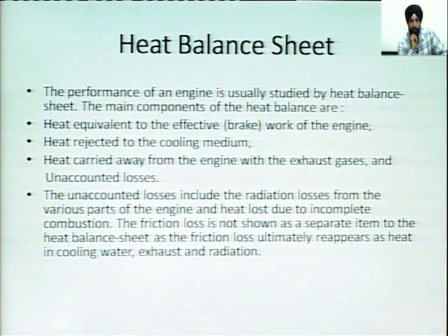The main components of the heat balance sheet are: the very first, heat equivalent to effective work of the engine or brake work of the engine. Second, heat rejected to the cooling medium or cooling water or coolant as the case may be. Third, heat carried away from the engine with exhaust gases and unaccounted losses.